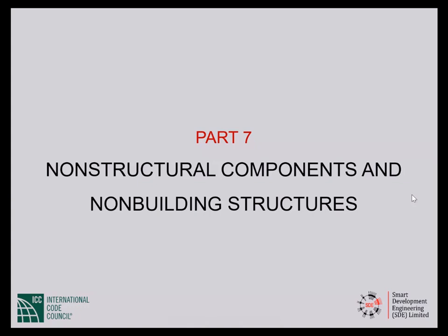This is a three-part question. Which load case and or combination shall be considered for checking drift? The real answer is that unless you have a very unsymmetrical building, gravity loads do not cause significant lateral deflection.